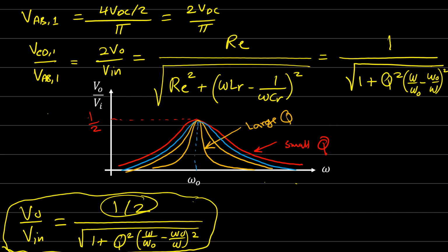So at this point, we finish what we call the series resonant converters. By the way, why do we call them series resonant converters? Because the whole rectifier circuit is in series with the resonant network, with the capacitor and the inductor. They are all in series, right? So the capacitor C_R and inductor L_R are all in series with the rectifier circuit.